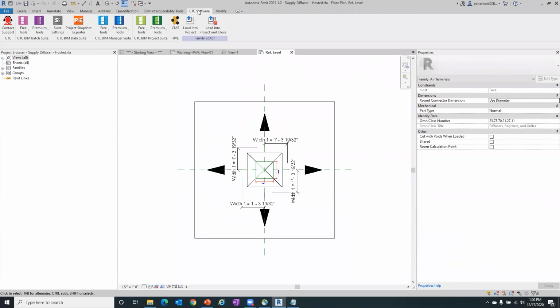We don't want users going in and accidentally deleting a shared parameter file. We probably want to have some IT control over where the shared parameter file is located, so if people need to read it, they can, but we don't want them to be able to delete it or move that file, because everybody is pointing to that location for a shared parameter.